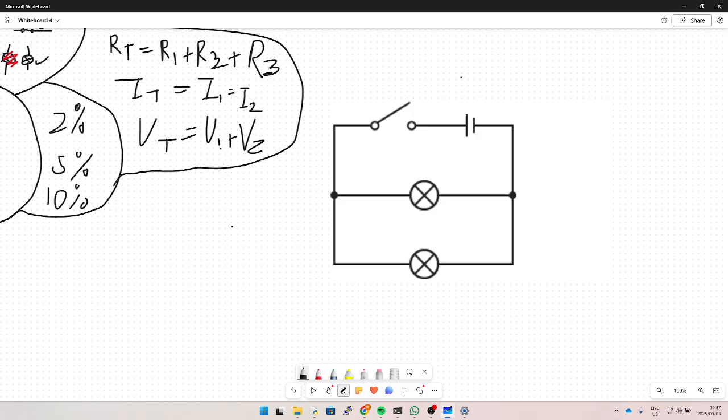Now, let's say this is 5 volts. The battery amps doesn't matter in this case. Now, what is the voltage drop across this bulb? This case, we're only doing simple parallel circuits, so I won't have you worry about that. But in this case, no matter where you measure this voltage, it will be the same. If I measure it here and here, here and here, it's still going to be 5 volts, no matter what. Because obviously accounting for the small tiny voltage drop, it will still be 5 volts because it's parallel.